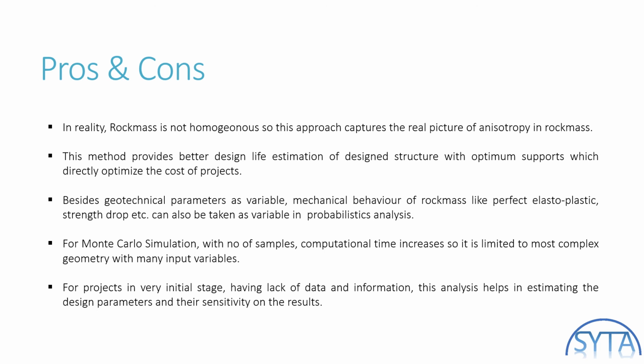And the very basic use of this approach would be for projects which are in a very initial stage, where we do not have much information about the geology or other geotechnical information. There we can very well establish some correlations and obtain some very useful results by varying the input parameters, which we can assume on the basis of engineering assessment based on nearby projects, or any minimum information available from the tender documents or any minimum investigation carried out at the project site.